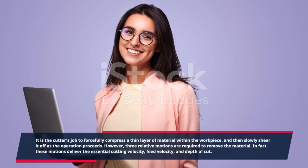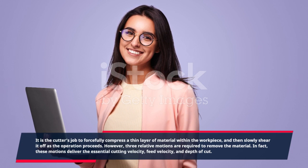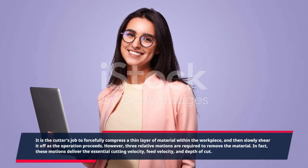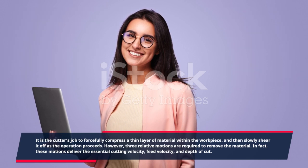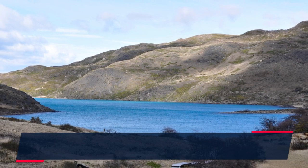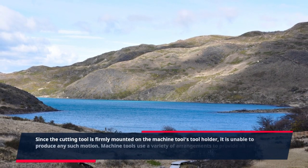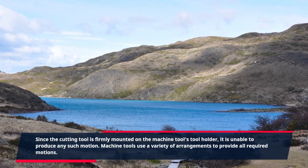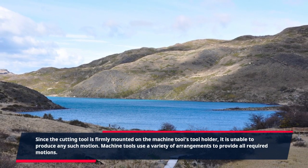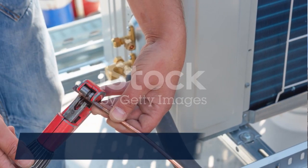However, 3 relative motions are required to remove the material. In fact, these motions deliver the essential cutting velocity, feed velocity, and depth of cut. Since the cutting tool is firmly mounted on the machine tool's tool holder, it is unable to produce any such motion. Machine tools use a variety of arrangements to provide all required motions.